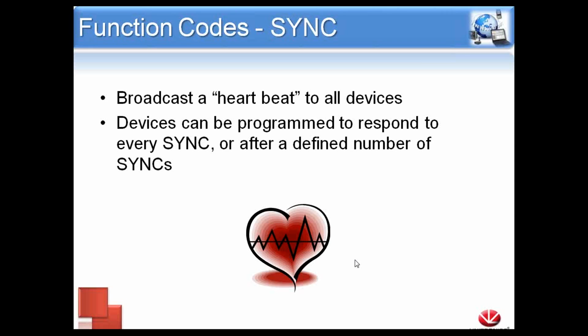Next we have sync. The sync command will broadcast a heartbeat to all the devices on the CAN bus network. And the devices can be programmed or configured on how to respond to those heartbeats. For example, I could say that on every sync, I want every device to report back its current values to my master controller.